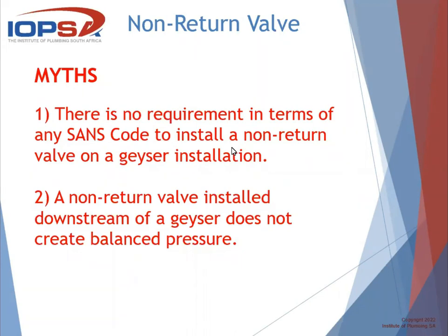And the intentions were good. The intention was, well, let's put a pump in, let's put a return line with a pump, and you can just switch this on, and this is what will result. The one was done as an afterthought. What that meant was that there was no lagging. Because the hot water reticulation piping originally was laid in the ceiling, it was lagged, but as it went down to various points, and there was a large portion of the loop underground, it was not lagged. And so that's one thing.